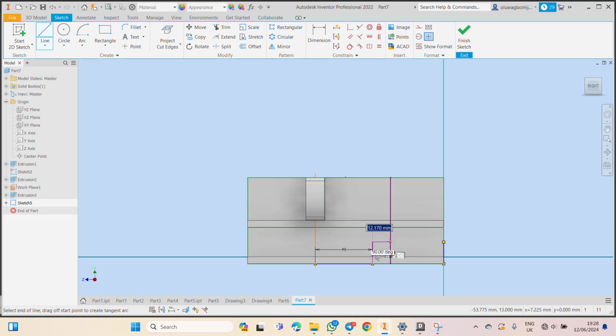Now to get the center of this part, the offset went in by 3. We're going to go to the right by 88 divided by 2. So 88 divided by 2 is going to be 44. Let's do that again. From here, this part, we have a 44. What's wrong now? From here, this thing, go to the right by 44.